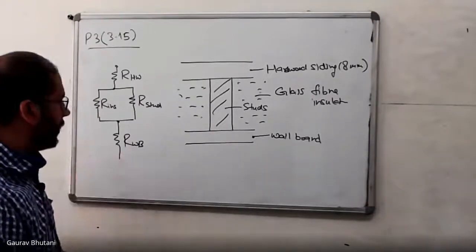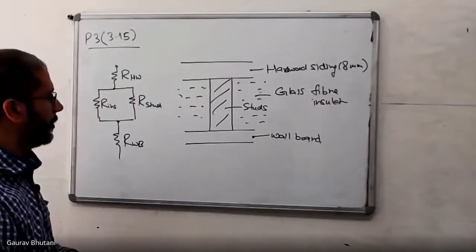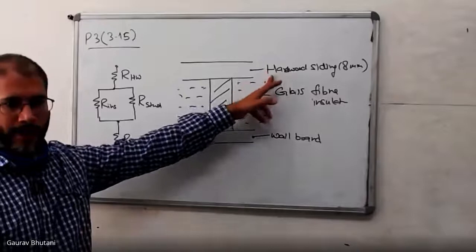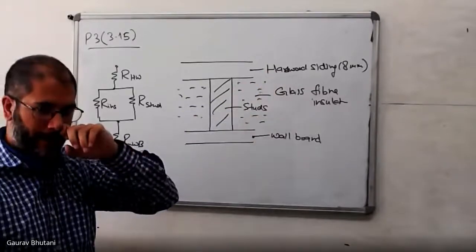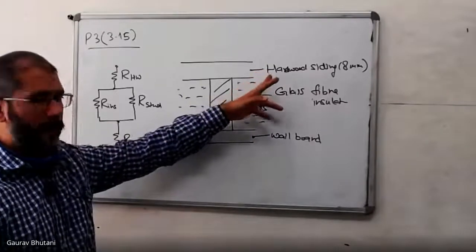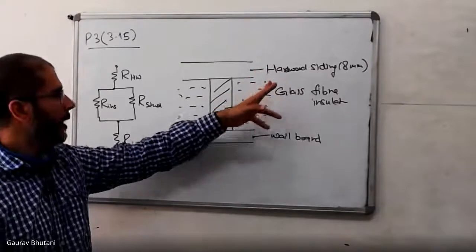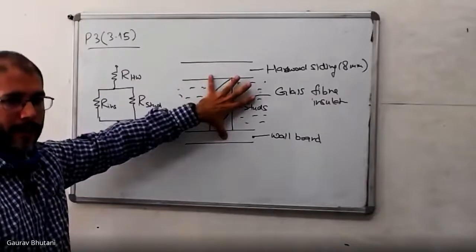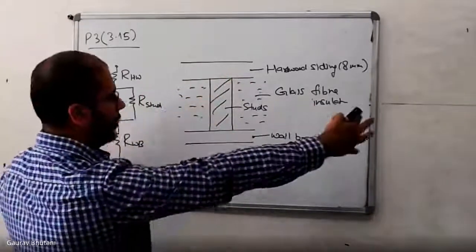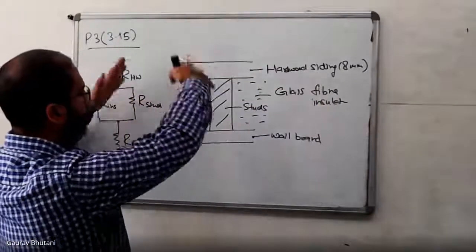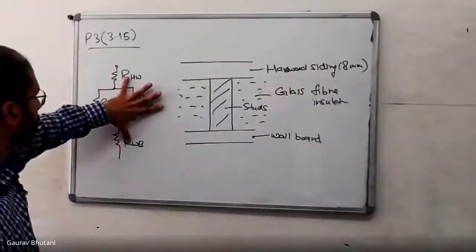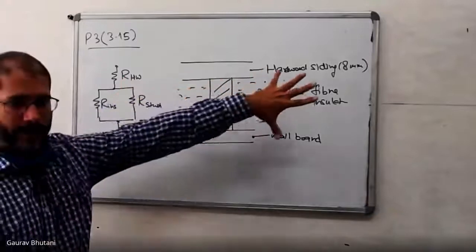So this is the net thermal resistance circuit that we have here. You can put the values of the thermal conductivities, seeing the tables and the charts that are available in the book, and then you can get the net thermal resistance of this one assembly. But remember, you have 10 of these, so the total heat transfer is split into 10 of those. That means the net resistance that you get here, you have 10 of these in parallel.